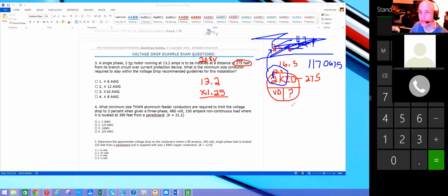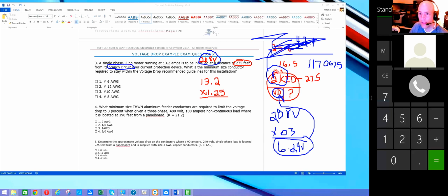And then for the bottom, the only thing I have to plug in here is this number right here. I know from our previous discussion that for 208 volt, the recommended voltage drop guideline for a branch circuit is 3%. So if I take 208 times 0.03, that's the maximum amount of volts I want to lose if I put my meter at the breaker and then at that motor. The most I want to lose is 6.24 volts. This caps our formula as the maximum amount we can lose, so when I plug it in, it forces this number to compensate to this exact value.